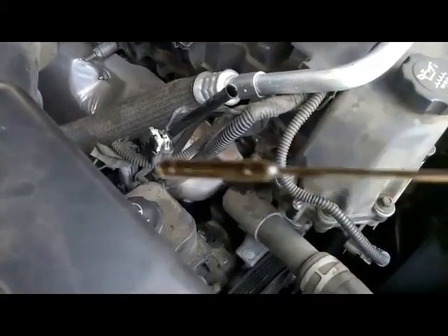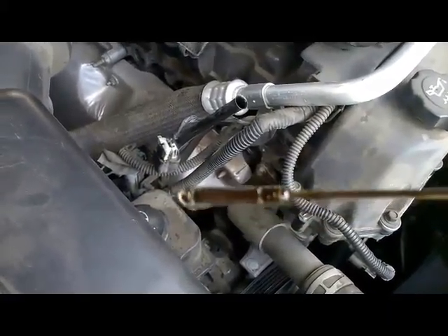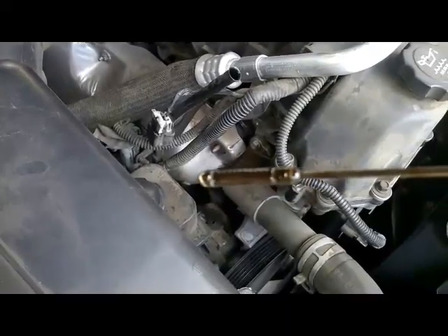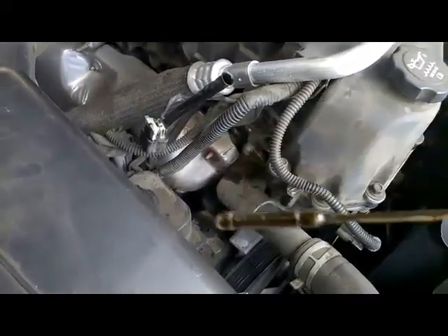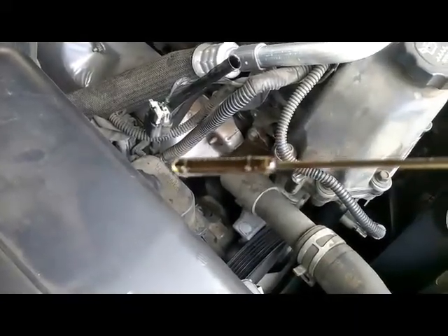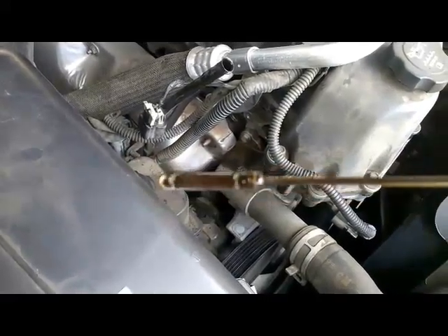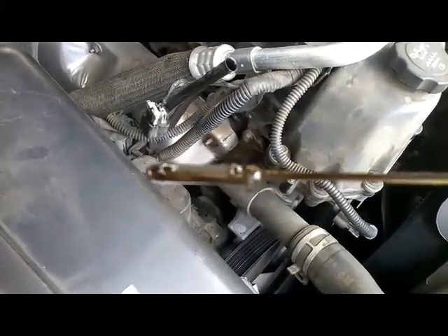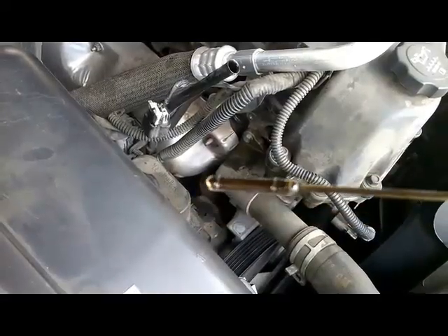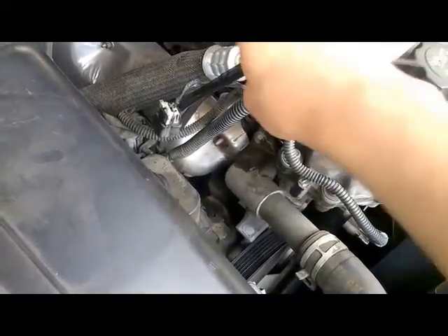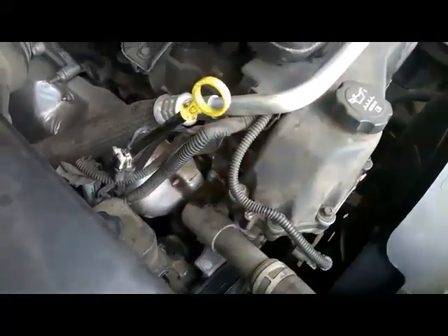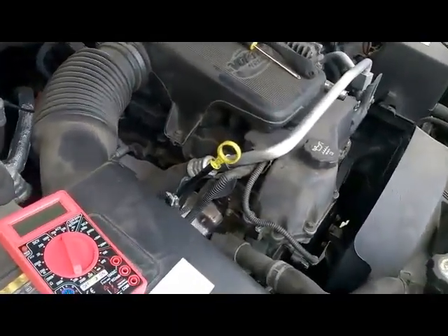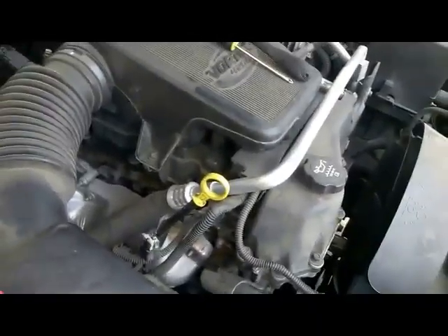The oil level looks to be within spec on one side, and on the other side it seems to be low. So I'm not sure what the oil level really is. But even if it's within spec, the oil pretty much looks worn out. It looks black, it looks dirty. I'm pretty sure if this vehicle has been running rough, there's probably contamination with the fuel. So that's another thing that I forgot to mention, is to also check your oil dipstick and oil level, because that's another common cause of this P0014.